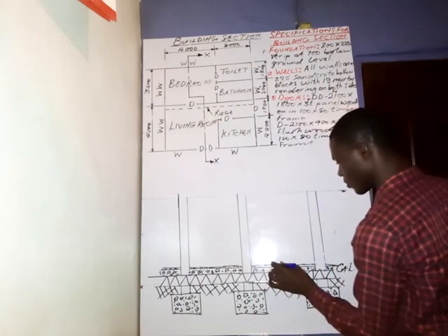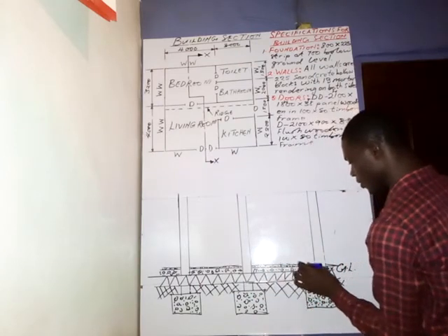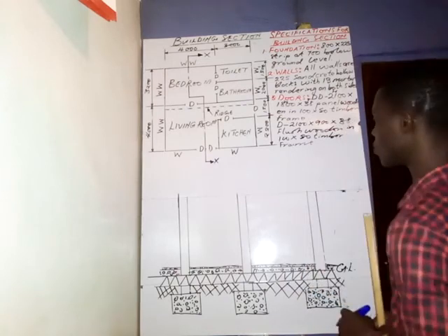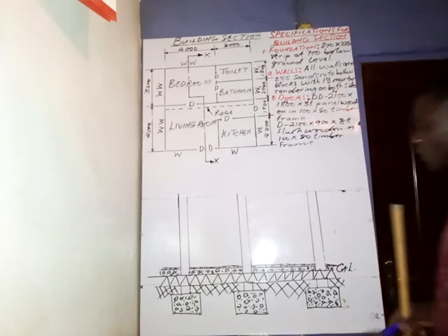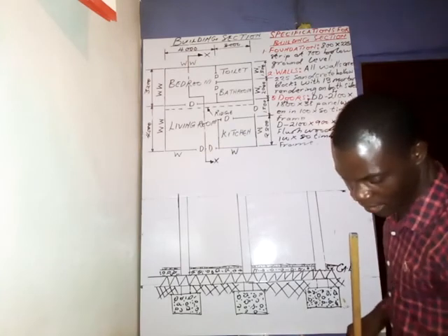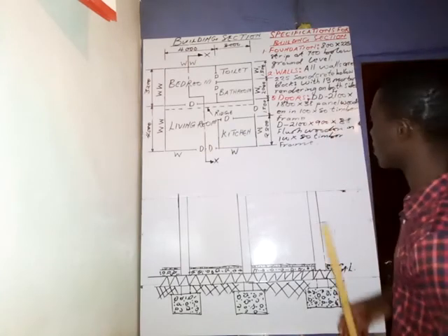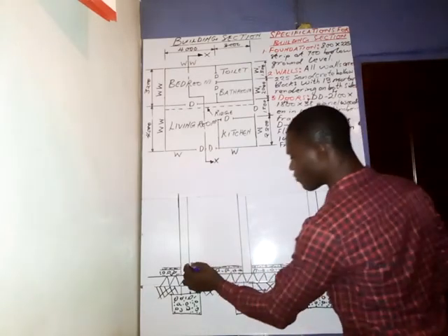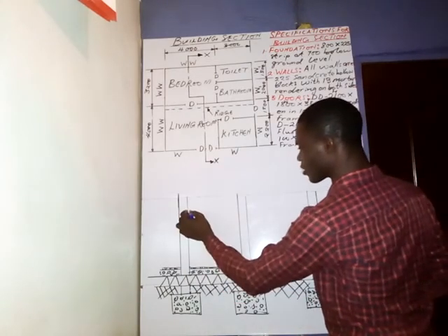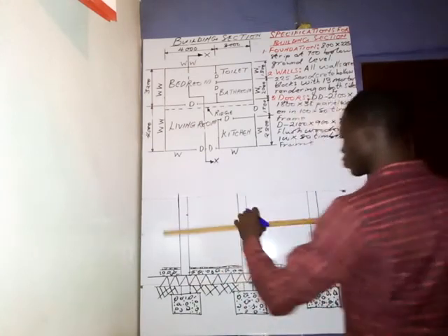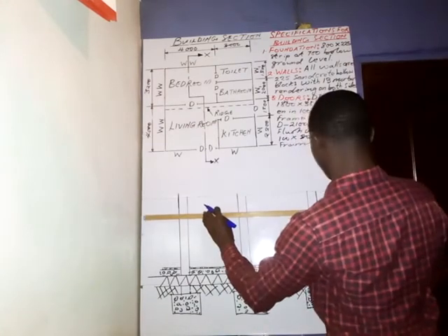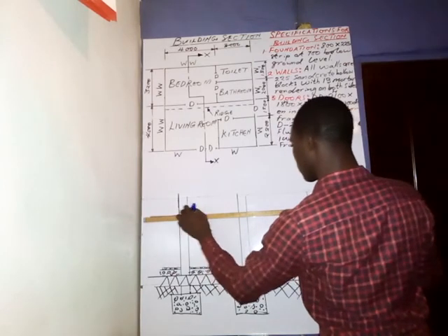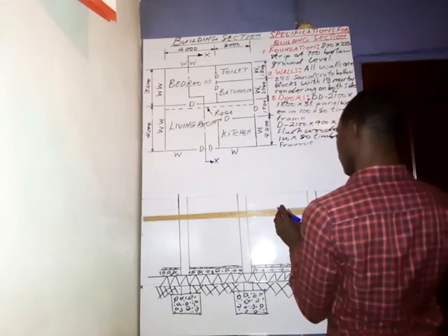Okay. So after doing this, the next thing that we are going to do is to take a measurement for the ceiling height space. After I divided by 50, it is 62. So from here to here, you take a measurement of 62 millimeters up and draw a horizontal line. Draw it like this, and draw it to this side.